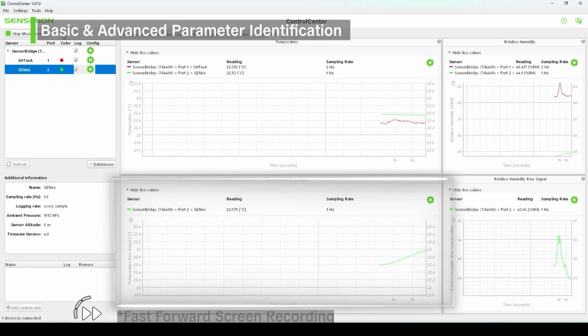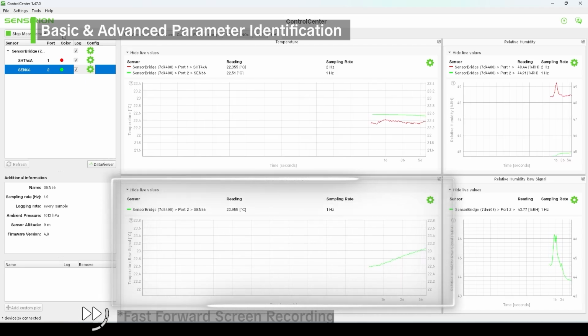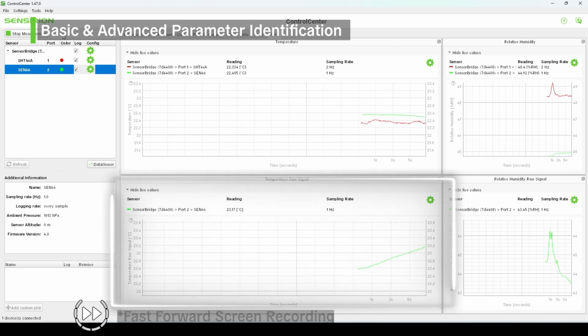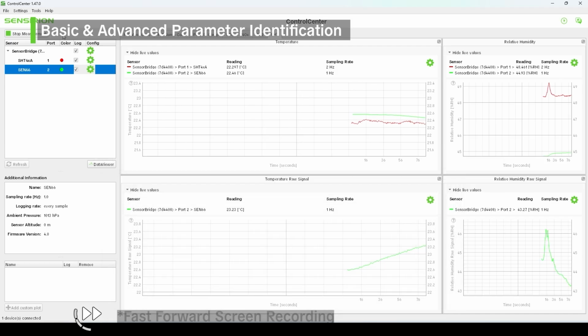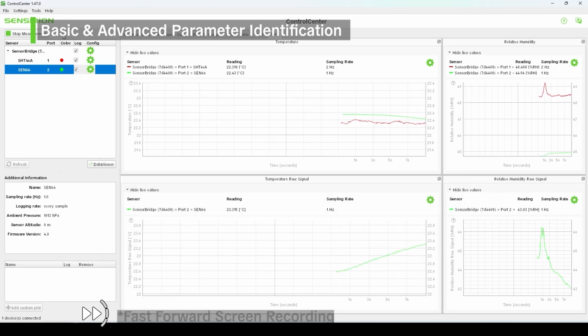Allow the device to heat up naturally. The Sen 6X temperature will gradually increase, which can be seen here at the bottom as the device heats up. If the signal has fully settled and remains unchanged for around 30 minutes, or at least for a meaningful period longer than just 1 minute, you can move forward.